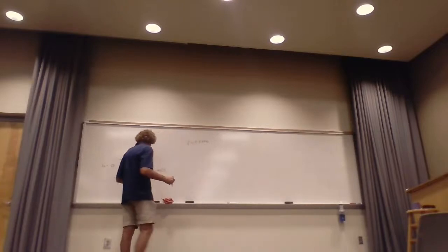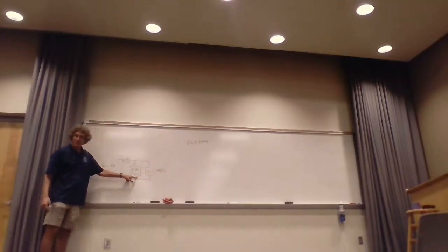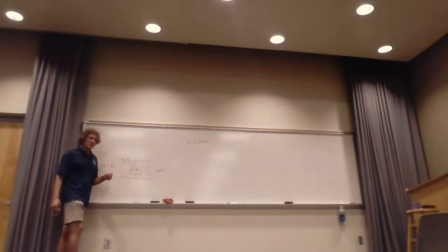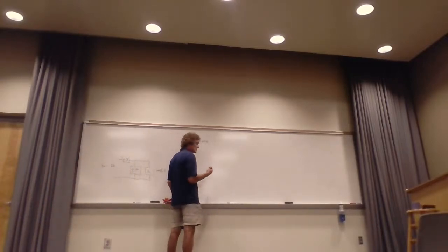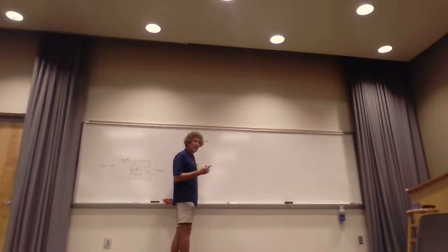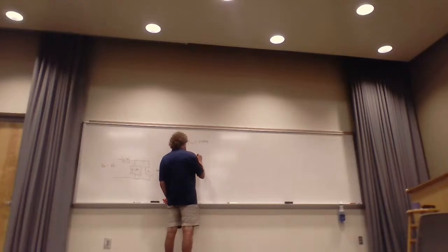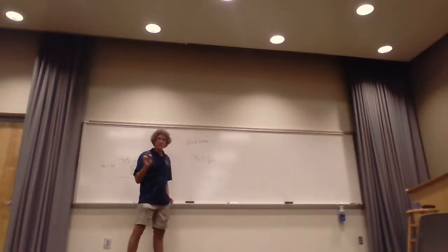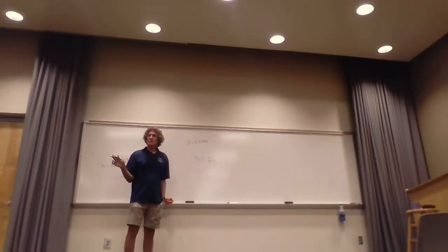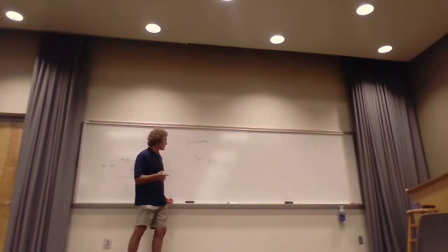This is an admittance, so we need a j1.34, right? The way I normally do this is to say, if I have two elements, I have inductors or capacitors. I know for sure that's going to be a capacitor, but I do it this way. I start with capacitive reactance as 1 over j omega C. This is the way I'm just showing you to do it. Then I normalize it. To calculate that value of capacitance, it has to be normalized.